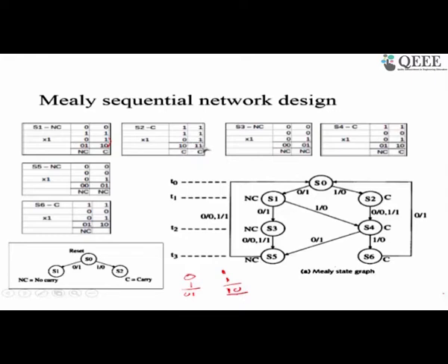On getting 1 we output a 1 and go to a carry state. So in both these cases we go to a state where we remember carry. So this state already remembers that. So we can as well go to the same state S4. Okay. So on a 0 0 or a 1 1 transition we go to S4.